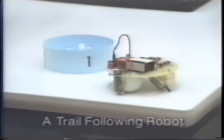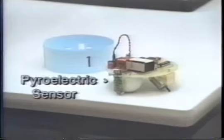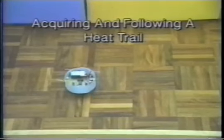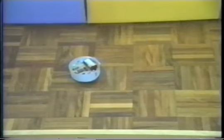A family of inexpensive robots has been developed at Monash University to investigate the practical problems and potential uses of similar short-lived markings. This particular robot carries a pyroelectric sensor as well as proximity sensing whiskers. This robot is programmed to search for and then follow a heat trail, while avoiding walls and other fixed obstacles. The heat trail has been laid by a larger robot carrying a 70-watt quartz halogen bulb.